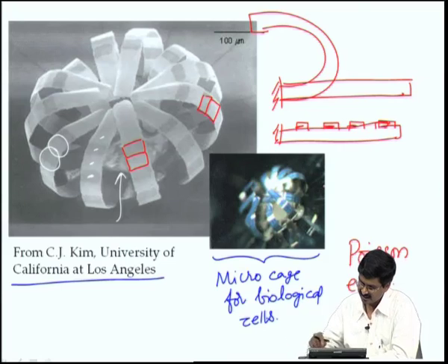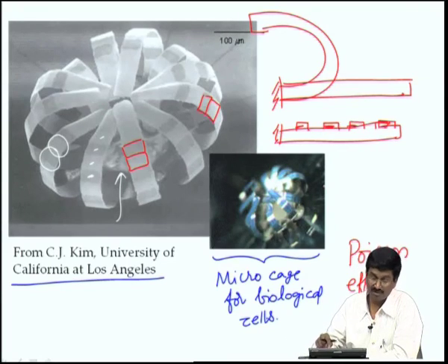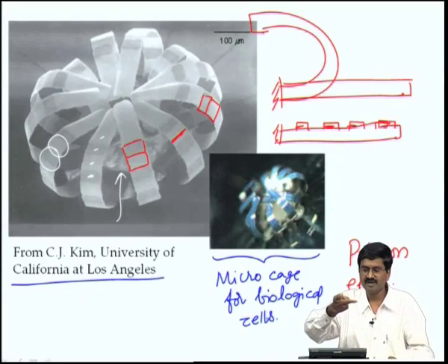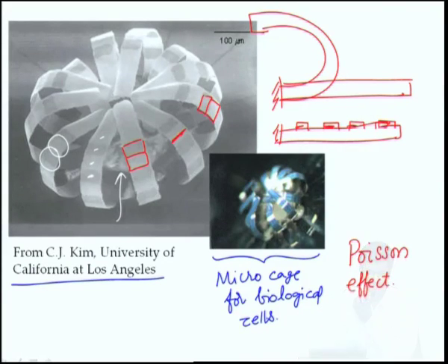And this has a lot of implications, especially in this particular example. If there is a residual stress gradient that causes it to curl like that, then perpendicular to this direction it will curl the other way. So, when my finger curls up in this manner, observe that if I look at this cross section, it will curl up like this. If I were to magnify this, it will curl up like this. So, one is going like this, the other would go the other way. Let us look at that in the form of a figure. If the beam is bending as shown here in this direction, in the cross section direction it will go the other way.